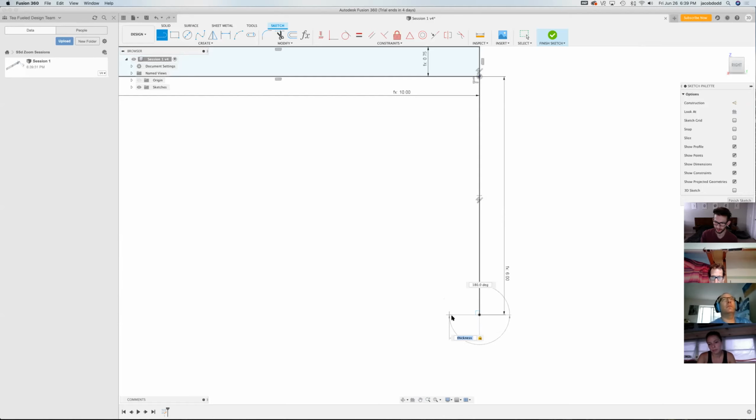So we'll just get it close to 90, let it snap, and then click. Because we're drawing lines, it already starts our next line for us because we haven't closed it off. We can either press escape, hit create and continue, or use that feature and drag it to meet the top line here. You can see that little symbol pops up near the intersection as a right angle.